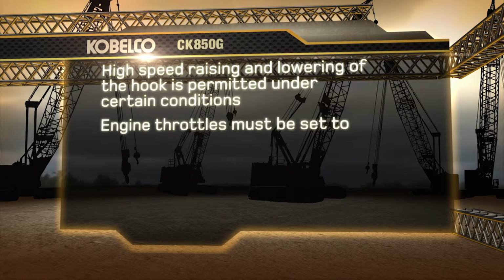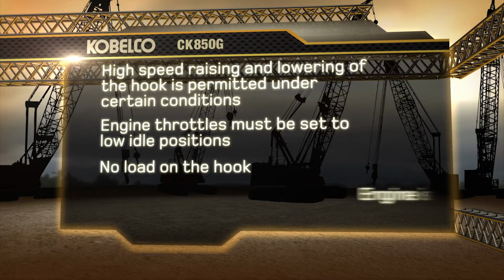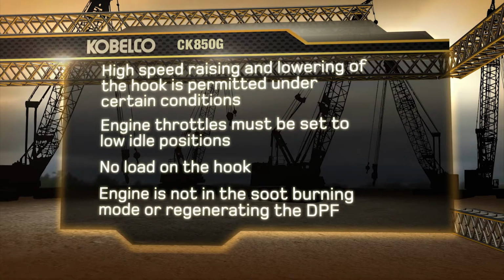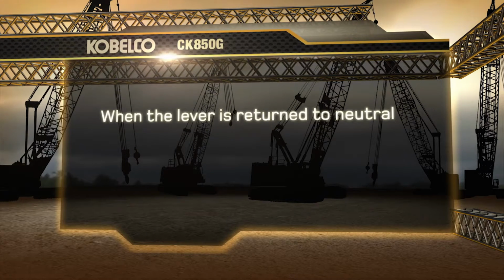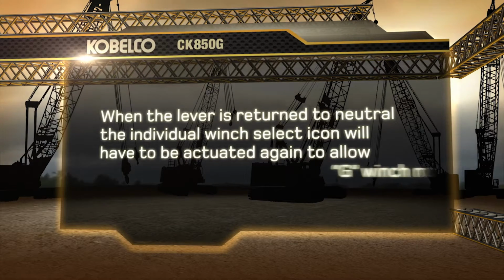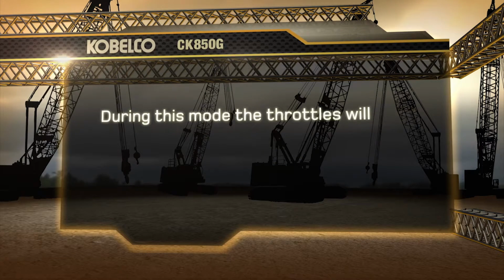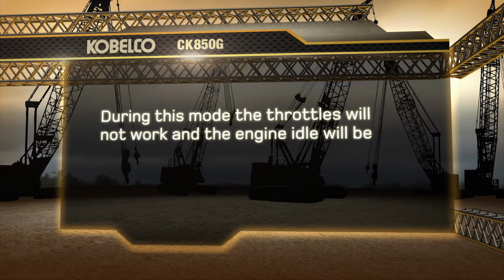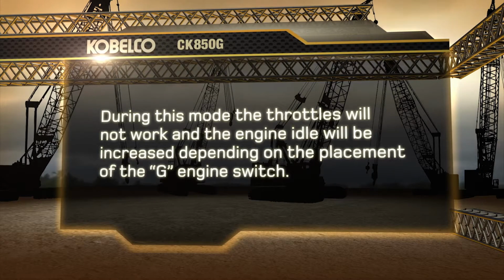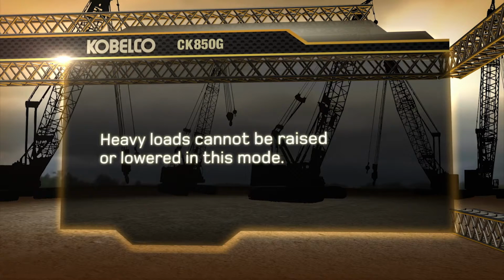The engine throttles must be set to low idle positions. There cannot be a load on the hook. The engine is not in the soot burning mode or regenerating the DPF. When the lever is returned to neutral, the individual winch select icon will have to be actuated again to allow G winch mode. During this mode, the throttles will not work and the engine idle will be increased depending on the placement of the G engine switch. Heavy loads cannot be raised or lowered in this mode.